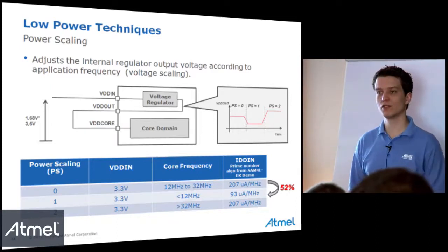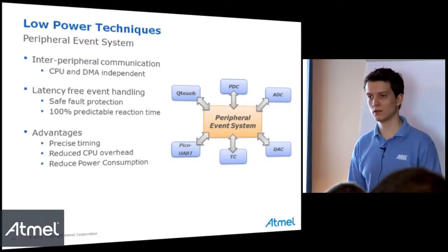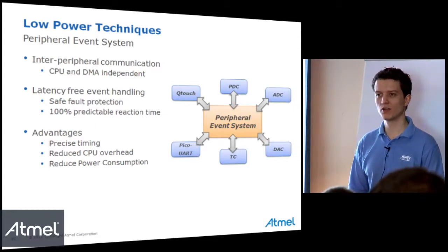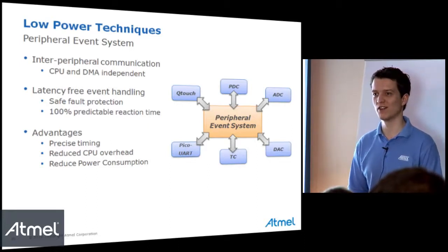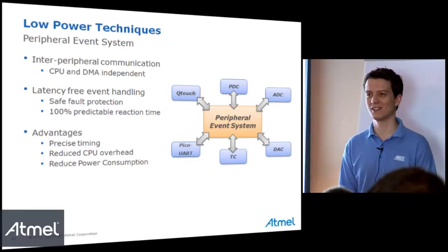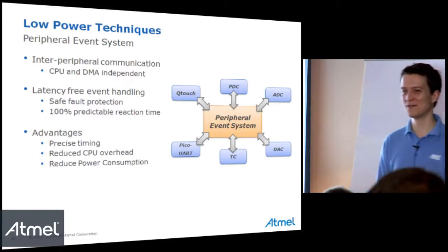Any other question on this topic? Is there any prevention if I'm running the wrong power scaling mode, let's say PS1, and I change my frequency? There is no prevention. You will just see a system failure. It will not be able to catch the instruction in flash, or it will be difficult to. So you need to be careful when you use this.